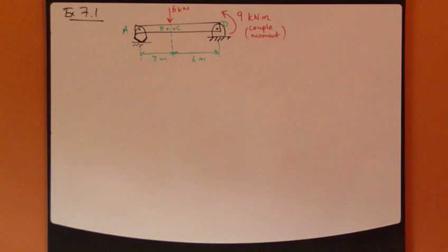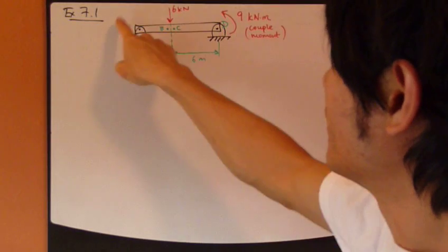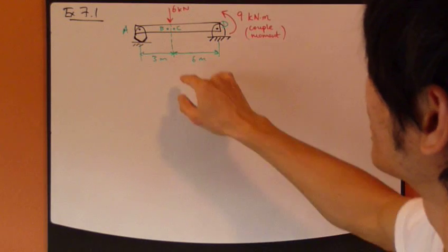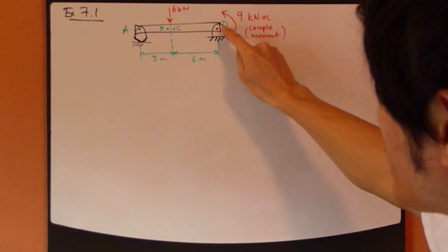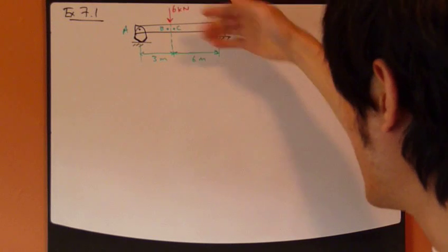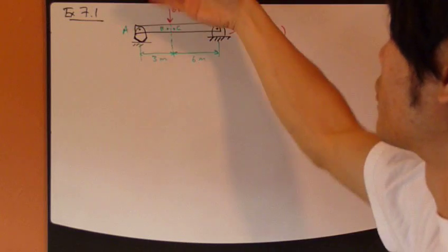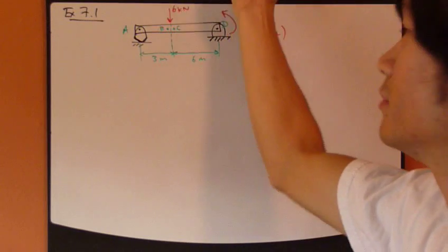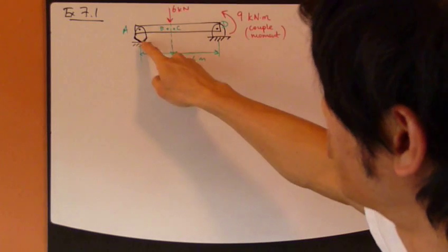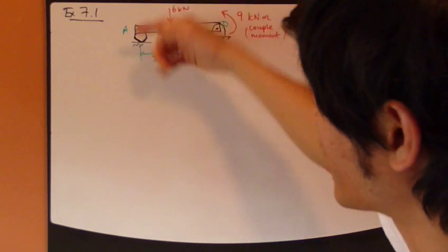Let's look at the structure right here. Now you have this rigid body AD, this little piece of metal, a beam. At D, you're attached to the ground, and it's a connection, so it's free to rotate. At A, it's just a little support, and that's all. It's not attached to it at all, so it's just resting on the ground.